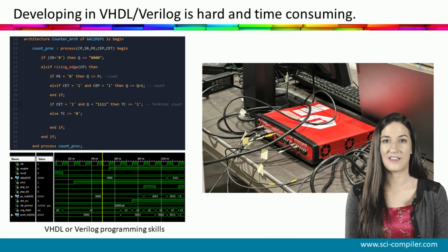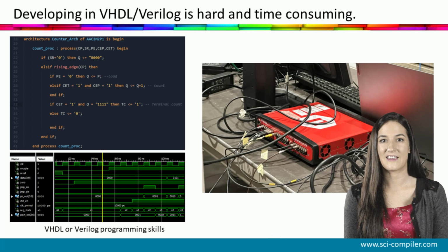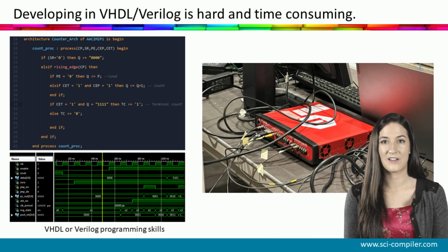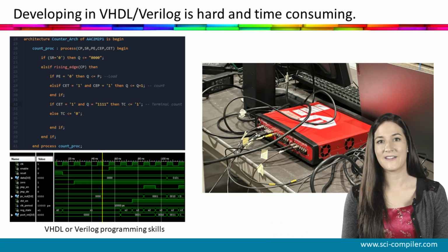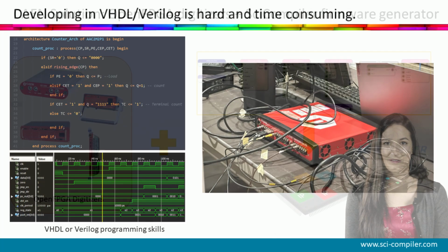Designing firmware for FPGAs demands proficiency in specialized programming languages such as VHDL or Verilog, coupled with an in-depth understanding of the electronic circuits that materialize when the FPGA compiler transforms the human-designed firmware into a machine-configurable file known as a bitstream. Typically, users articulate their desired logic functions or algorithms through code. However, the compiler's output more closely resembles an intricate electronic circuit rather than traditional software. This complexity significantly steepens the learning curve for those looking to harness the full potential of FPGA devices.